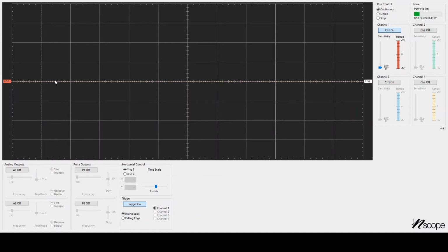And the trigger says when the voltage in channel 1 goes, on a rising edge, through the intersection of these two dashed lines, then we'll show the data. So what I'll do is grab my trigger value and move it up to, here's 2 volts. So when the voltage goes up through 2 volts, we will show the voltage. Of course, my scope crashed, so open it again.